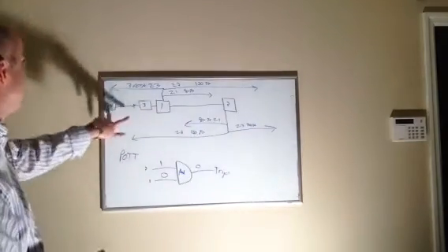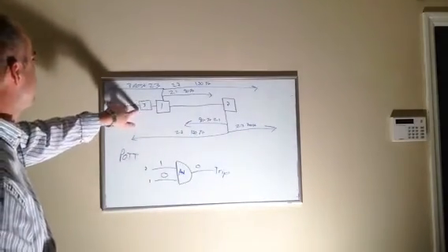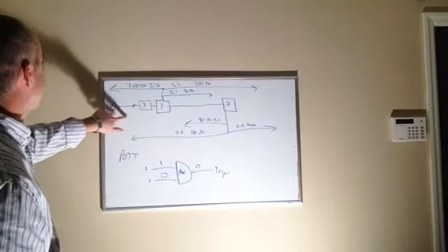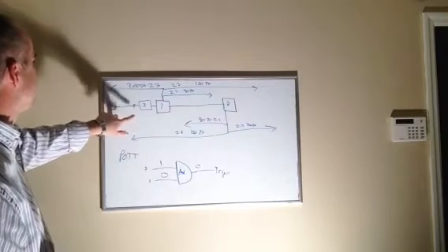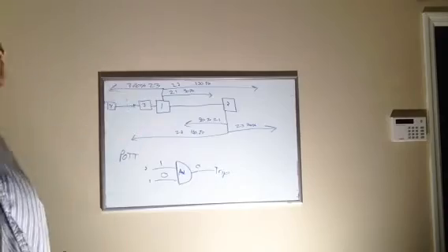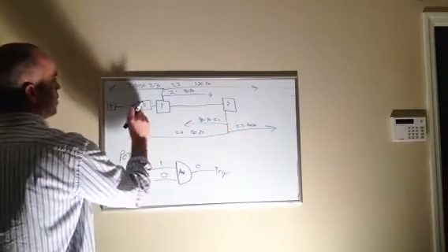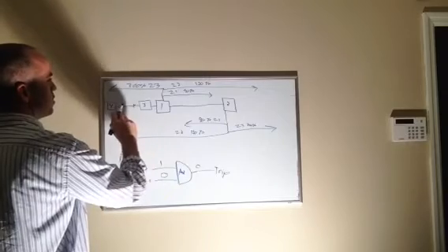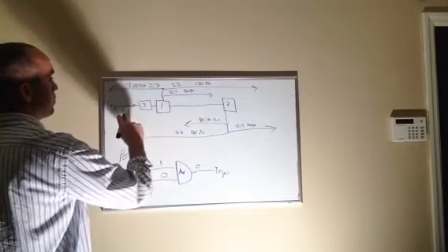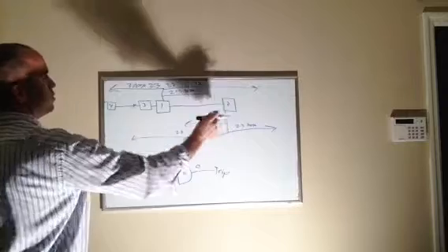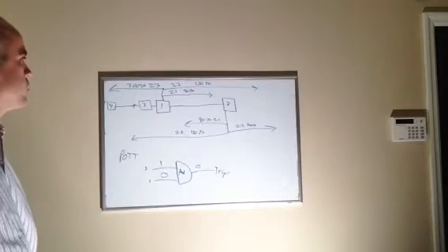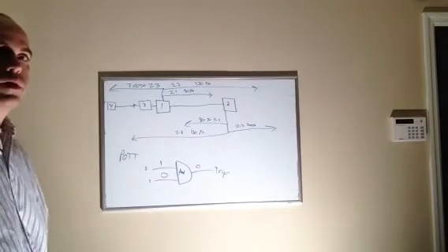But if you look at this line, this breaker is going to see it forward looking, and this breaker is going to see it forward looking. So both of these breakers are going to trip high speed. And then this breaker should never operate unless one of these breakers fails to clear the fault. If one of these breakers fails to clear the fault, then zone 2 would trip in 20 cycles on a time trip. So that's how POTT works